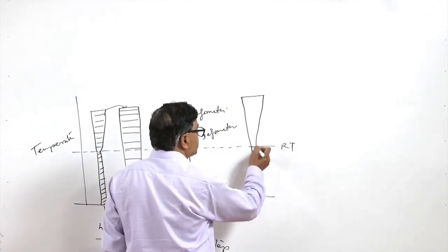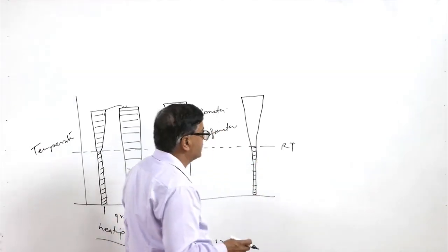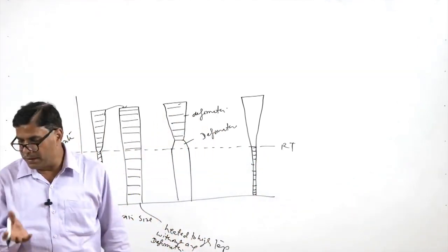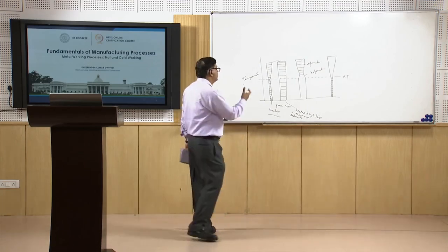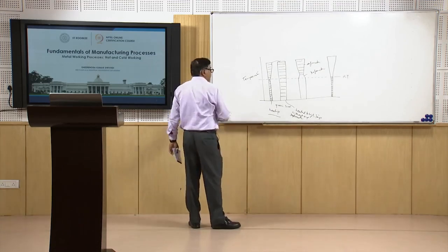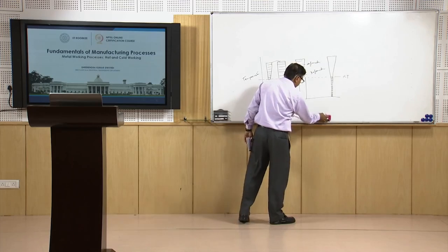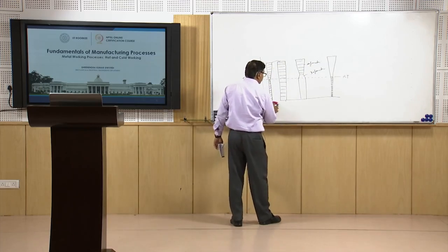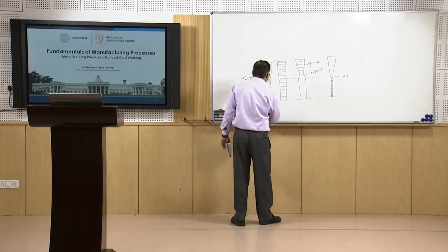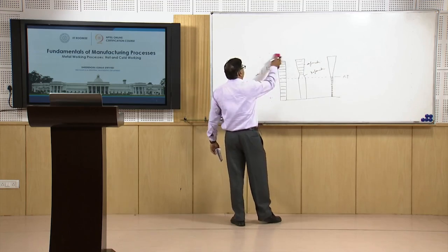And if the deformation is continued below this recrystallization temperature, then due to the lower ductility and higher strength, metal may get cracked. So, that possibility is also to be avoided. So, this is what we can see happens when the metal is heated to the high temperature with and without plastic deformation.